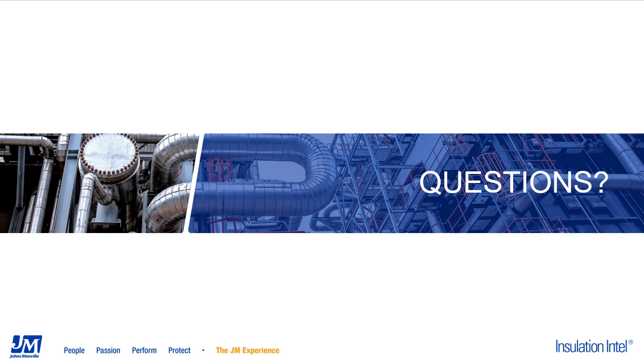So Scott, the first question is for you: I am particularly interested in insulation materials that can operate at 900 degrees Celsius. Okay, 900 Celsius is going to be somewhere up around 1650 F, if I'm not mistaken. As you recall from our presentation, all of our products are rated for a maximum of 1200, except for our Super Cal Temp 1700, which is rated for 1700 degrees Fahrenheit.